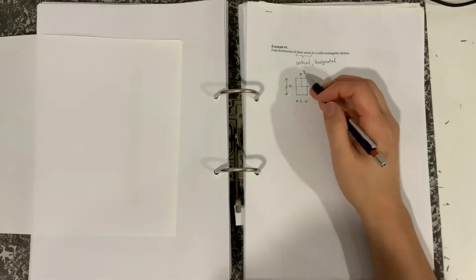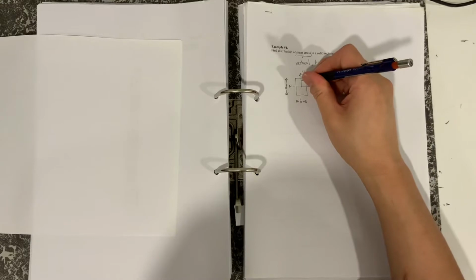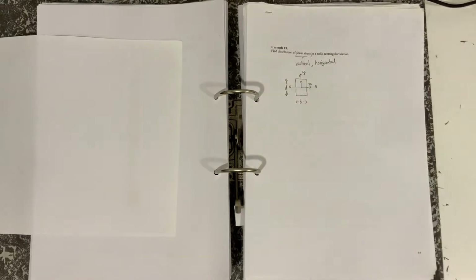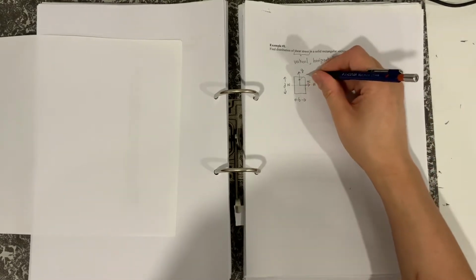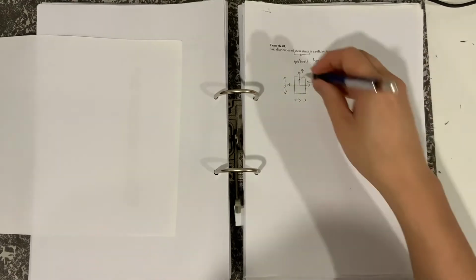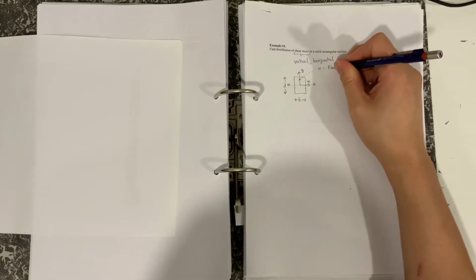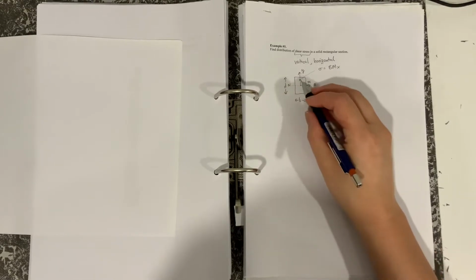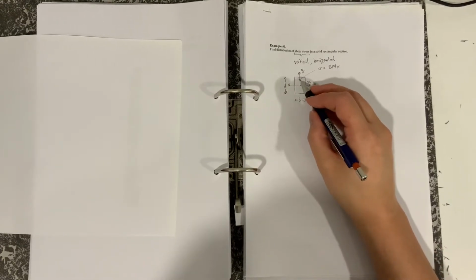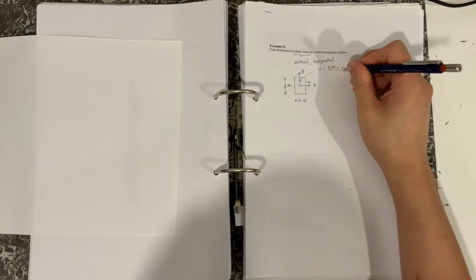So if the rectangular section was under a bending moment M, and we want to calculate the stress at that point there, we would use sigma, which would be the stress acting in the page, equals the bending moment from the bending moment diagram times y, which would be the height at that point there. So that would be y, which is the axis. So y at that point, sigma equals My over I.